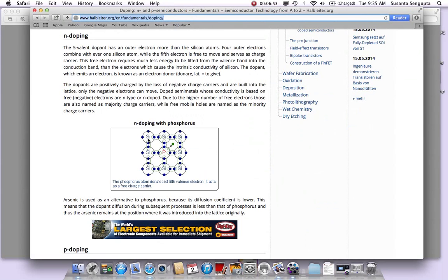But see, this is a silicon structure, right? This is a silicon atom which has 4 electrons around it. Each silicon has 14, but it only has 4 electrons at the very outside of those bands. It has various bands, right? Some of them are very closely attached to the core of the atom, but some of them are not so strongly attached to the core of the atom, and that number here is 4. So these are the 4 electrons of the silicon atom.